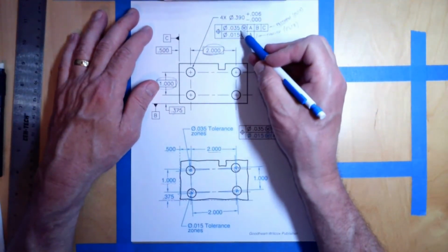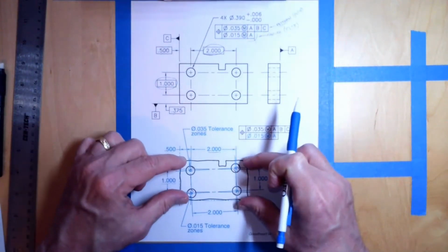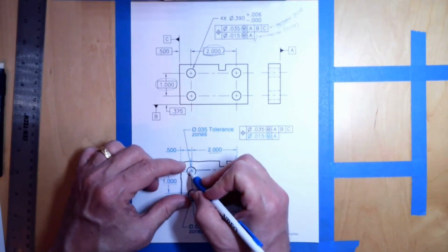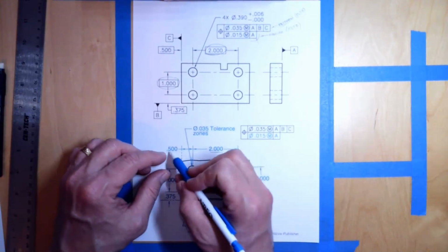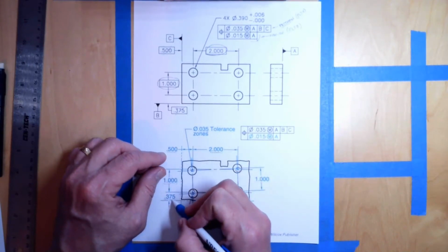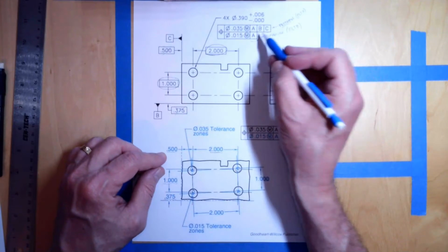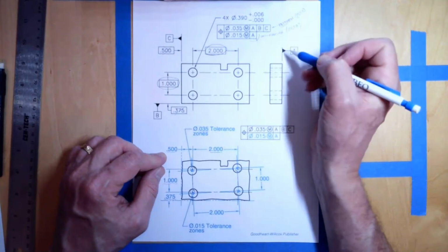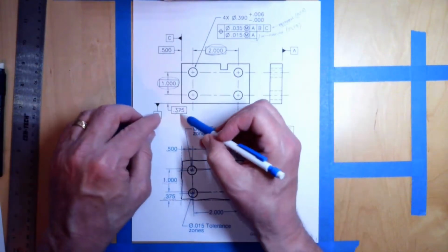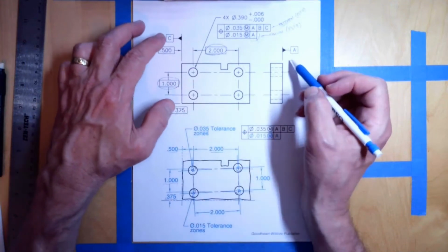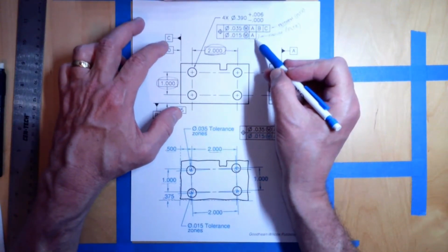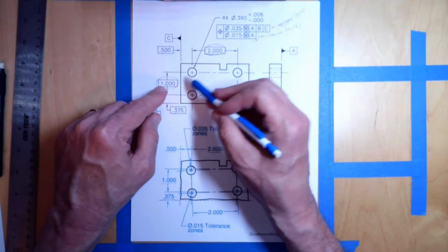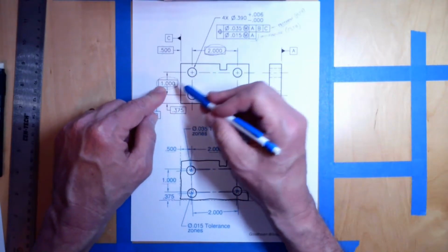come into play. Okay? The pattern locating tolerance zone just says that the 4 holes can be in a larger pattern, provided that they are appropriately located from the datum reference frame, A, B, and C. The feature locating tolerance zone says we're not going to worry about their location relative to, in this case, B and C, but we want to still ensure that they are located relative to each other.